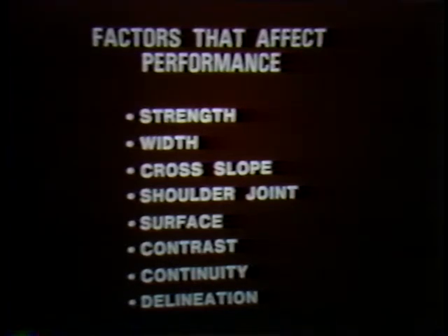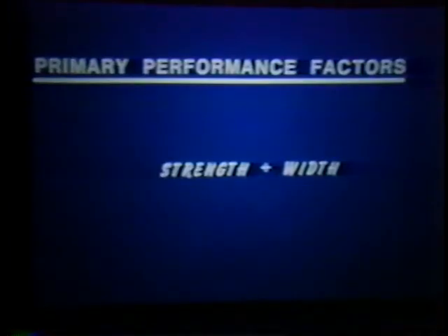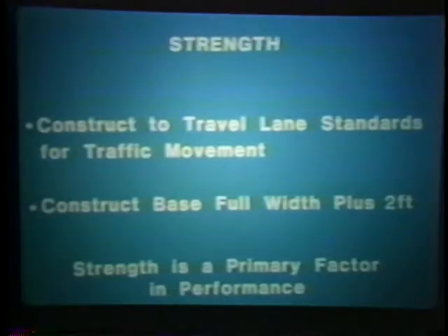Some are structural, others are related to drivers. Shoulders need strength to handle repeated wheel loads and width to permit vehicles to drive on them. Without the proper strength, the shoulder does not function, and maintenance costs increase. The standards of the shoulder's construction will determine its potential use. A weak base or surface construction will not stand up to repeated wheel loads or to erosion. So certain requirements need to be anticipated for the construction of effective shoulders.